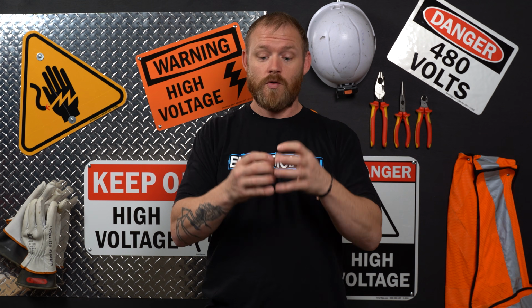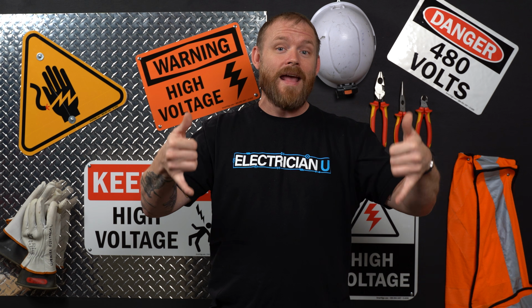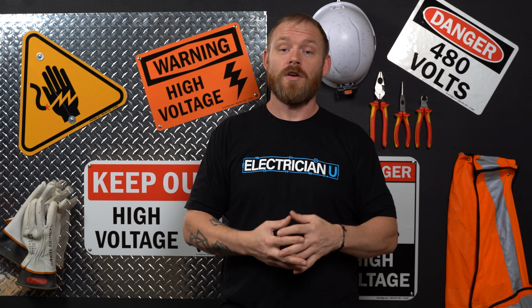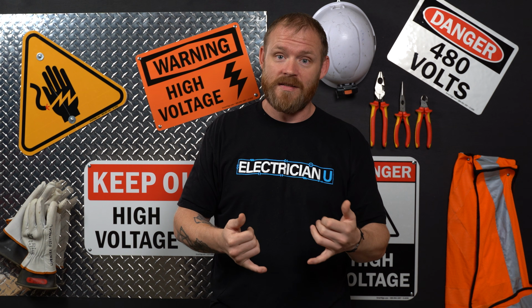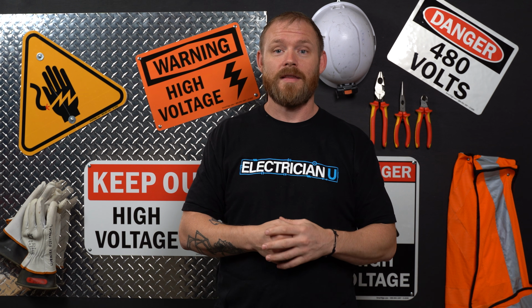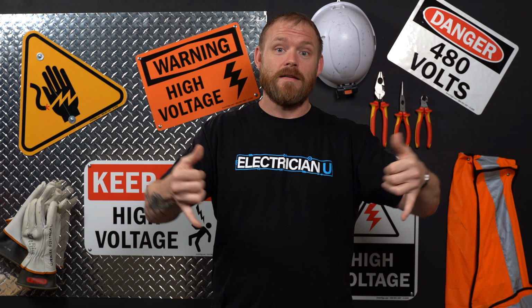Or if you're running them in parallel, the voltage is always going to be the same, but you're adding amperage. So the capacity of how much fault current can travel through a circuit is huge the more that you start stacking batteries in parallel. If a battery short circuits, you could have tens of thousands of amps, like in a car battery, if you short circuit that, and that's crazy dangerous. But if you start adding batteries in parallel, then you're increasing the capacity for more fault current for every single battery that you install.